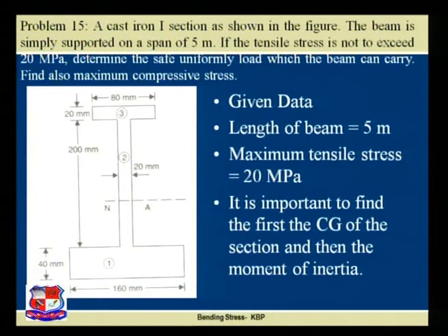Now it has been stated that the limitation on the bending stress, specifically the tensile stress, is limited to 20 megapascal, 20 Newton per mm square. What is the question then? Determine the safe uniformly distributed load which the beam can carry.